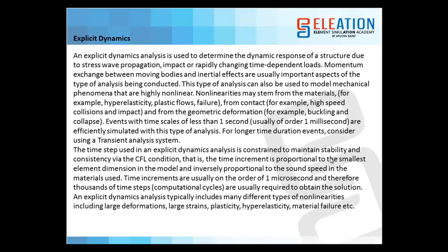Then one more thing on day 4 which we are going to see is dynamic analysis on the roll cage. So what exactly does dynamic analysis mean? We'll see in brief. An explicit dynamic analysis is used to determine the dynamic response of a structure due to stress wave propagation, impact or rapid changing time dependent loads.